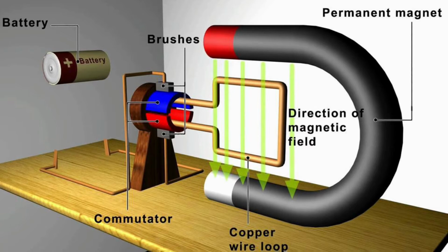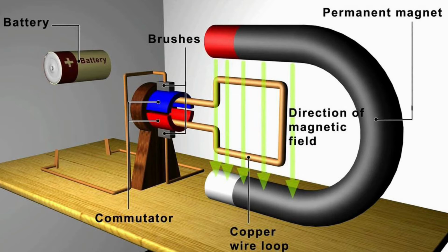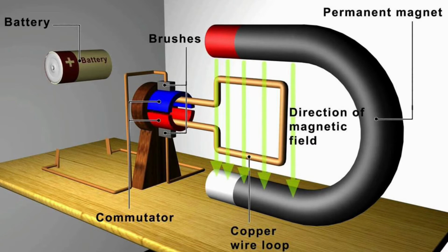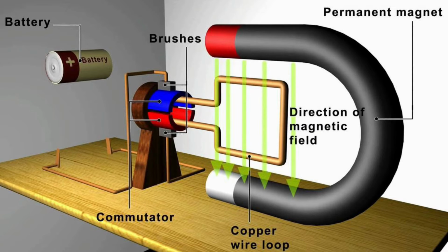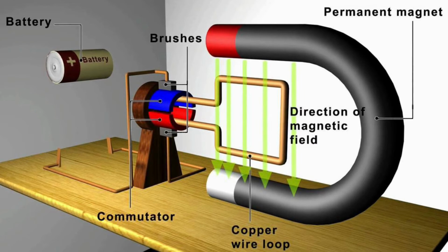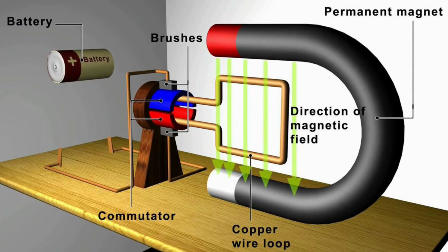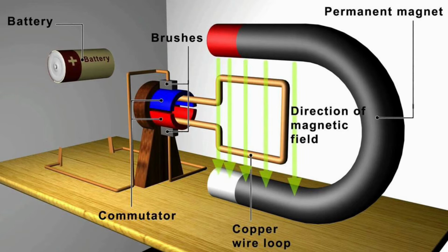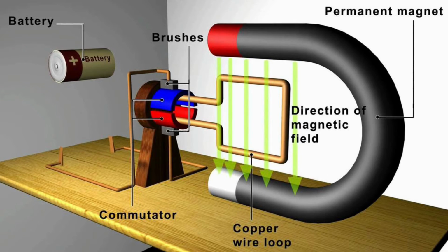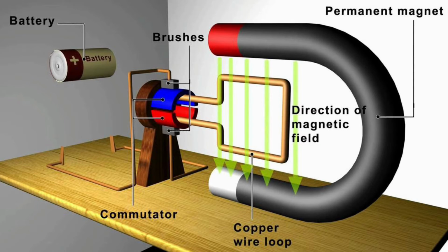And as the coil rotated, it induced electromotive force or EMF. We can calculate by EMF equal NBAω sine theta. Next, we have commutator and brush to prevent the tangling of wire as it rotates.